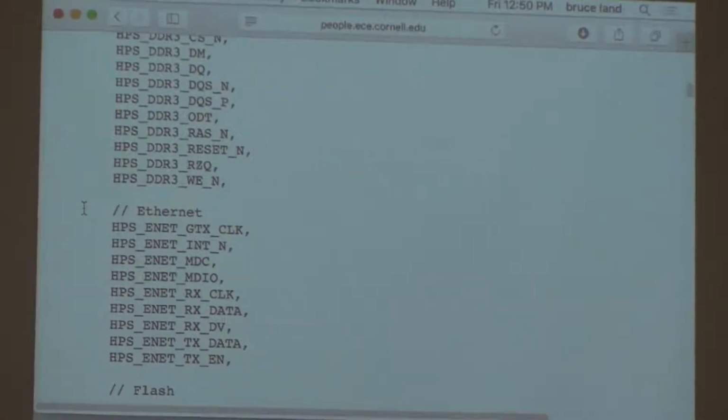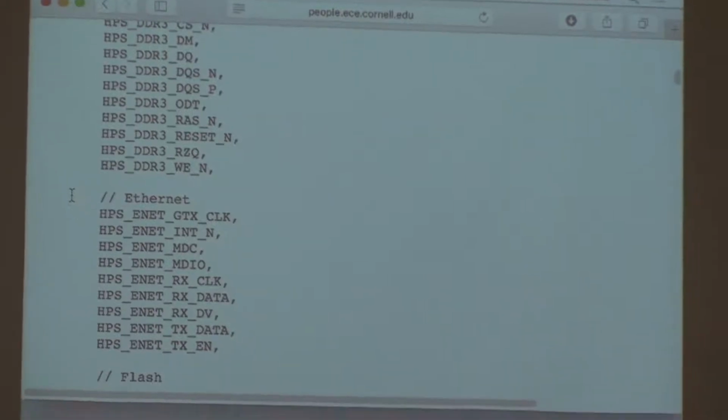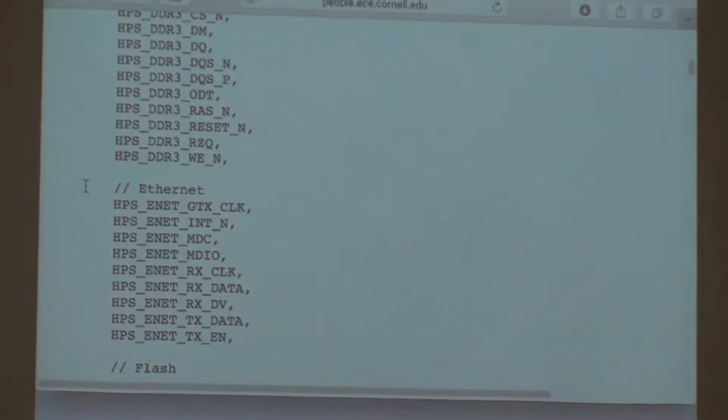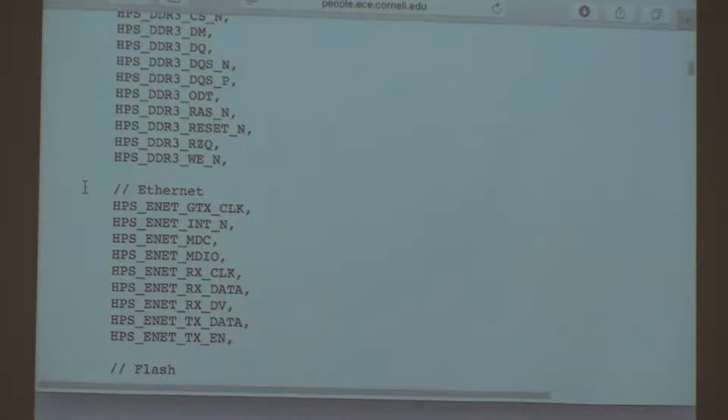I did that because sooner or later this is going to grow into some sort of graphics application. The modified controller that uses only SDRAM and no on-chip memory is in this code if you want to use that instead of the default memory setup for VGA.